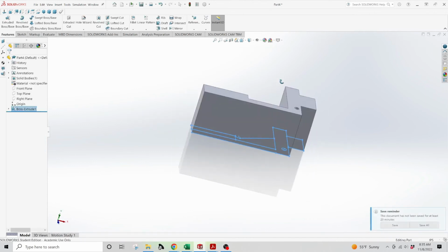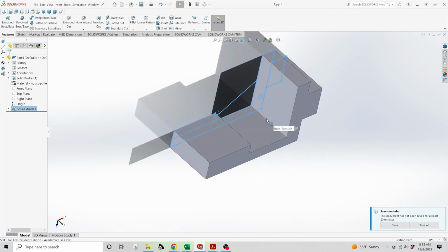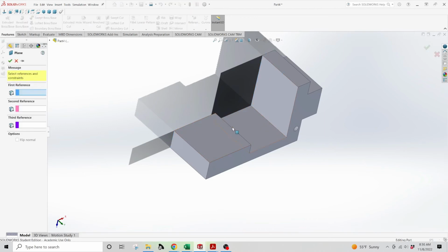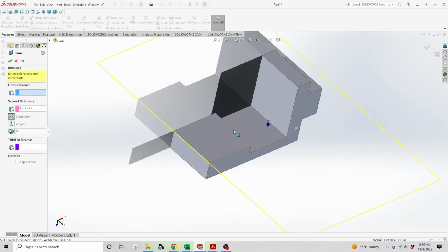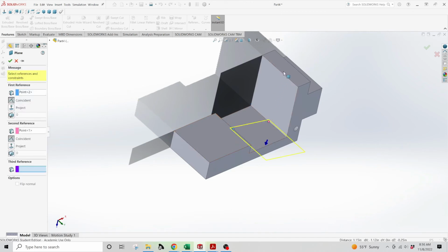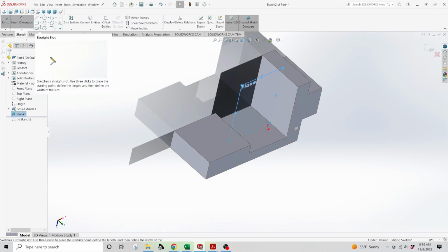All right. So even though this looks nothing like it, we're going to make a couple key pieces. In order to do the rib justice, the easiest thing to do is a reference point. So we're going to need to change that edge to a point, and then find a point up here. Because 3 points defines a plane, we're going to do one more extrude for that rib.